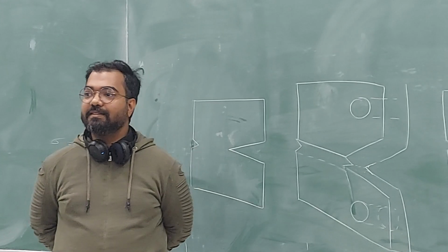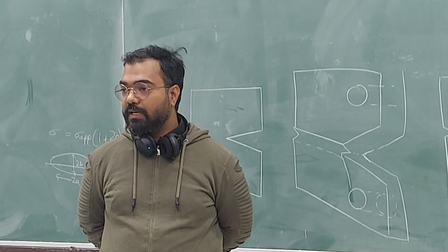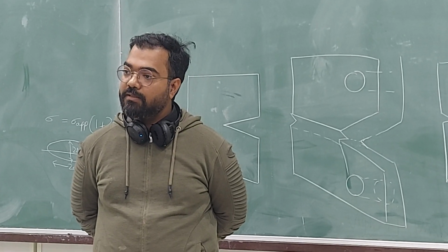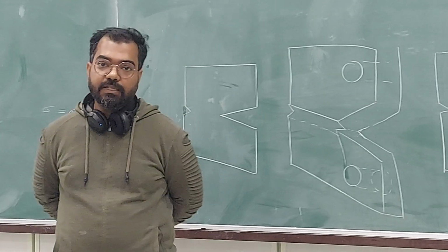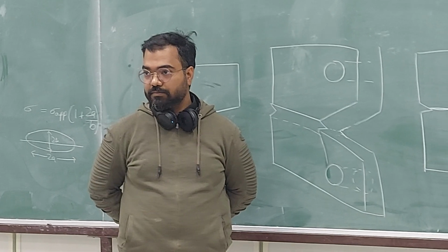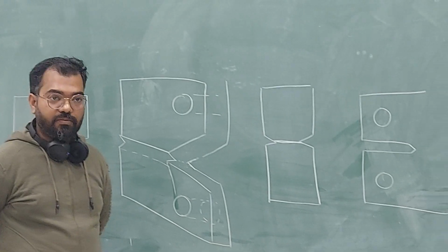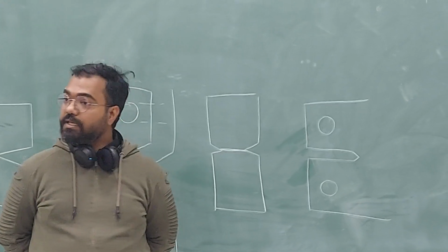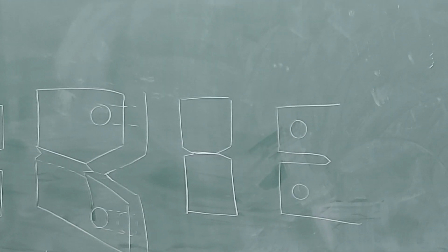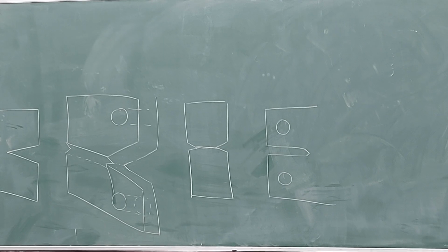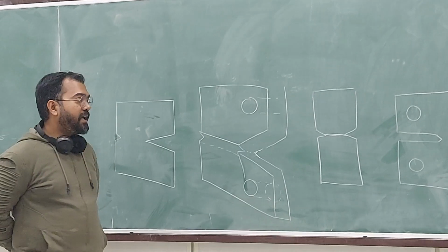Any tool will be finite, so then how will you make a crack which is that sharp? So that is done by fatigue, by loading it under cyclic forces, and then a crack initiates, and that crack is initiating not because of any tool, that crack is developing because of fatigue damage. Okay, so then you will have a hairline crack.